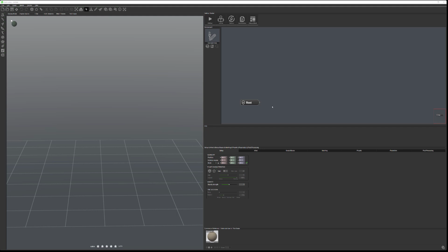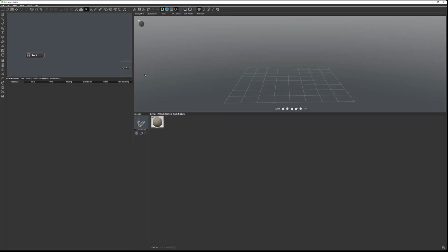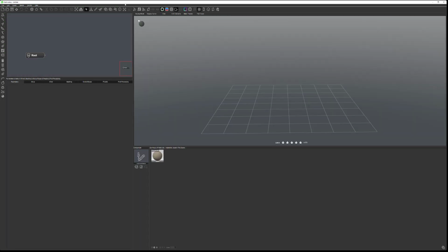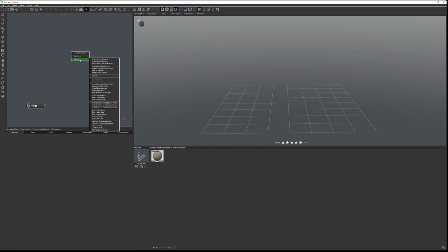Personally, I highly recommend you slightly adjust this basic view. If you go to display, workspaces, and switch to advanced, personally I prefer this mode because it allows us access to a toolbar and a little bit more options. As well, we have a few more options on the side for the node, fast access with our toolbar, and some additional properties. So next, what I recommend you do at the beginning is right click on the nodes, go to options, and right here we can enable a couple of options.